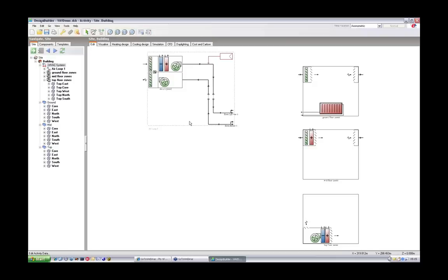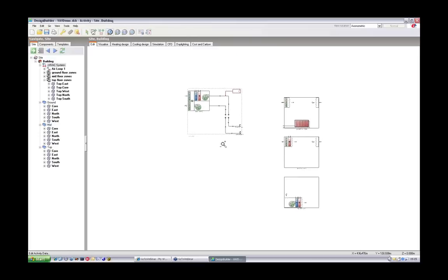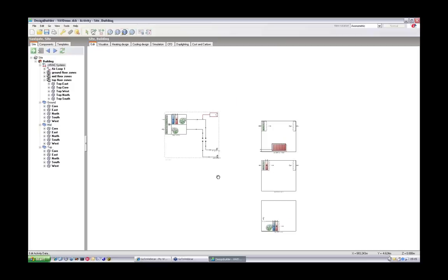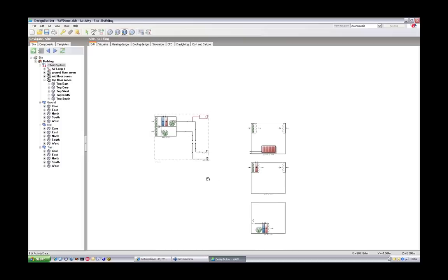Okay, I've now defined the air loop, the zone groups and zone equipment. So now I need to add plant and condenser loops. The air system that I've put together incorporates both water heated equipment and water cooling coils. So I'll need to include hot and chilled water plant loops together with a condenser loop for heat rejection from the chillers. So first of all, I'll zoom out and pan to create some room to add the additional loops.